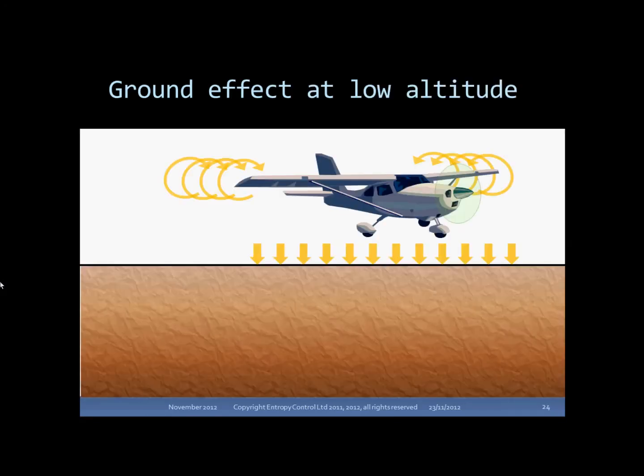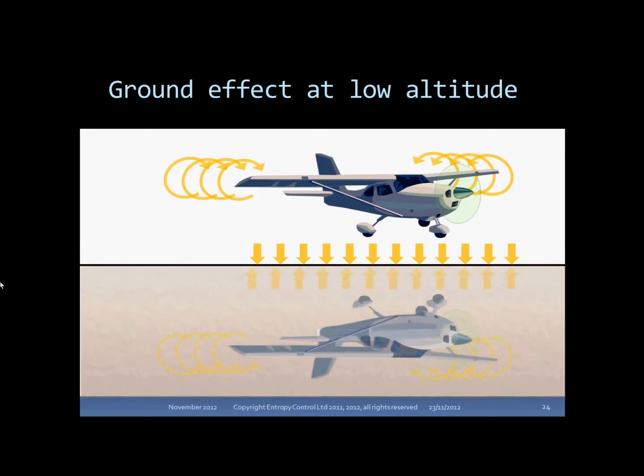The second case of ground effect is what you're more familiar with. When an aircraft is within about half the wingspan of the ground, the ground can be thought of as an aerodynamic mirror. The phantom aircraft flying upside down under the runway is creating a very real updraft into which the real aircraft is flying. So the real aircraft is essentially partially gliding in its own updraft, which results in a marked decrease in induced drag. So if you come in a little fast, you float and float and float in a low drag regime, just when it would be nice to have high drag so you can get down.